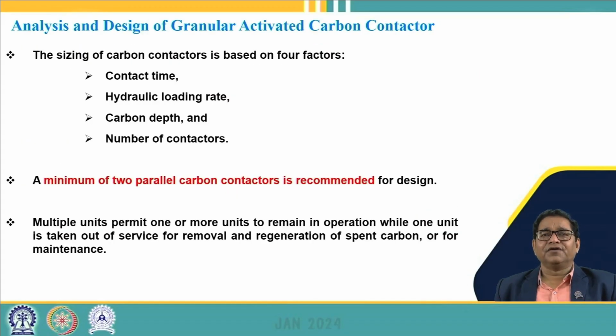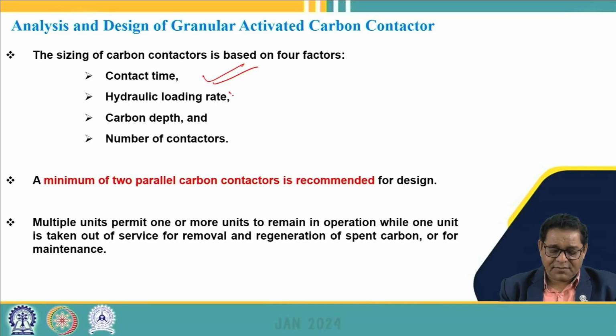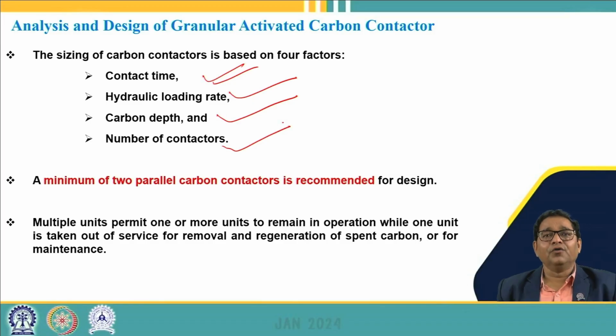So again, the major aspects of the design of granular activated carbon are contact time, hydraulic loading rate, depth of the activated carbon, and how many units we have to design. A minimum of 2 parallel carbon contactor units is designed, but in case there are multiple units, one unit we can keep as a standby and the rest of the units will keep on working. As some of the units require regeneration, one standby unit is always preferred for this granular